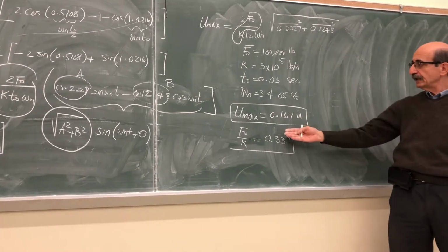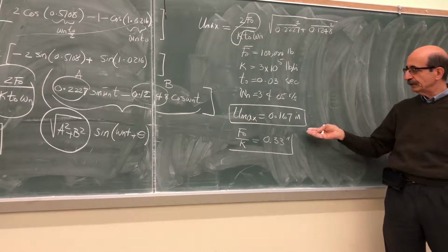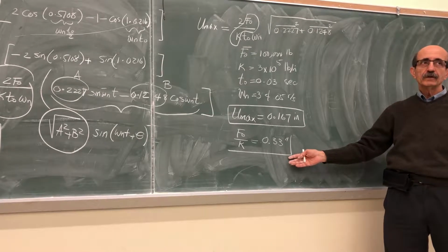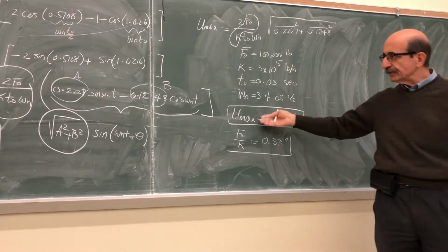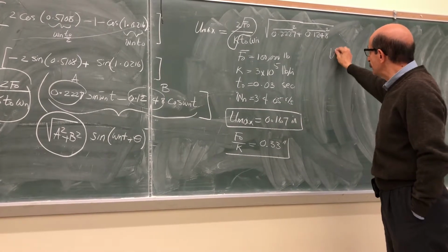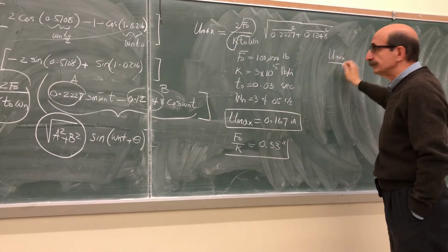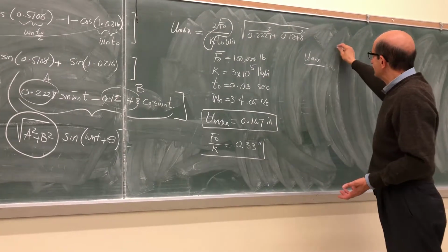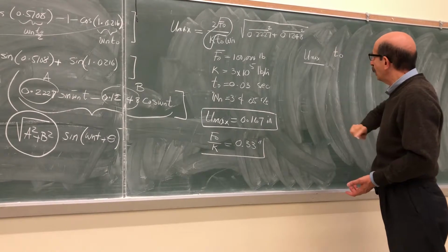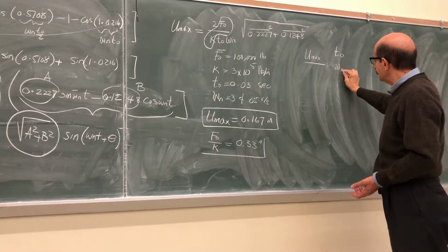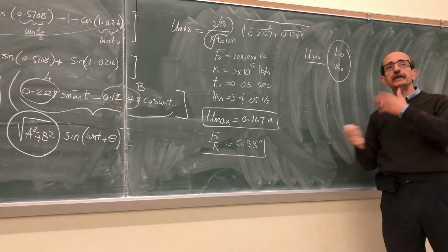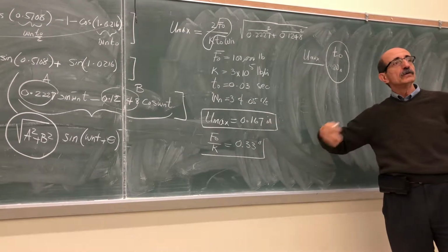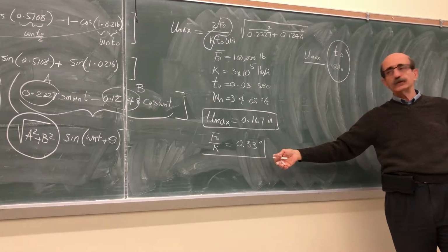In fact, in this case, as you can see, the maximum dynamic displacement is almost half the corresponding static displacement. So the reason for that is that the maximum displacement under any kind of short duration loading, which we call shock loading, is a function of two variables: time duration of the load and the natural frequency of the system. Depending on these two, you may have a response that is worse than the corresponding static displacement, or in fact less severe.